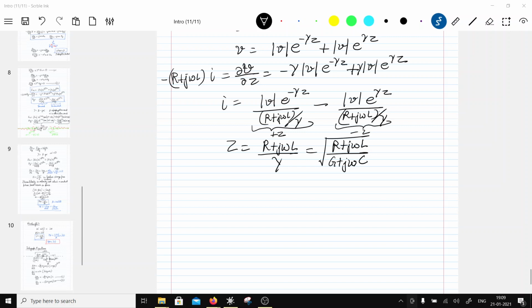So I'm simplifying a lot of things here for you. It's just that when you read something, it can be along with the loss, and the loss can be dielectric as well as conductive, right? So these things I am just keeping out of these equations, but you can always write it in terms of tan delta, right?